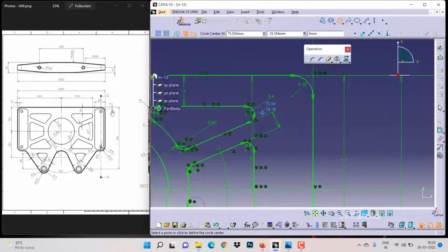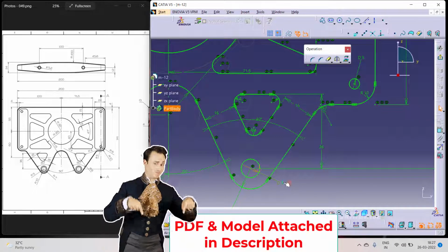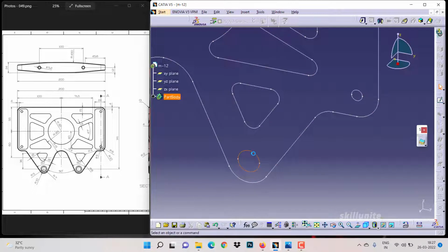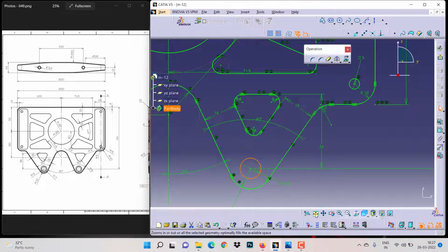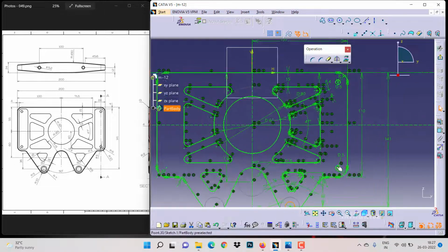As you can notice over here it is concentric, so that means here I can make it. The only thing I need to mention is the diameter. So it is going to be diameter 5 mm. The other diameter is going to be 10. Then click on okay, sorry, we have to mirror it. So just zoom out a little and select the object whichever you want to mirror. Then click on the mirror tool, then choose your center axis.